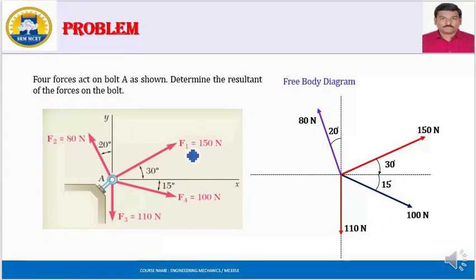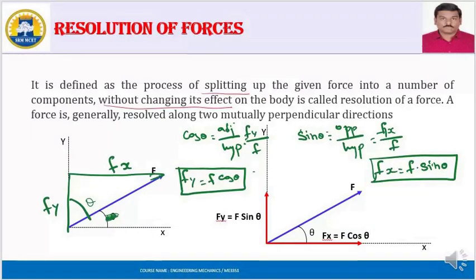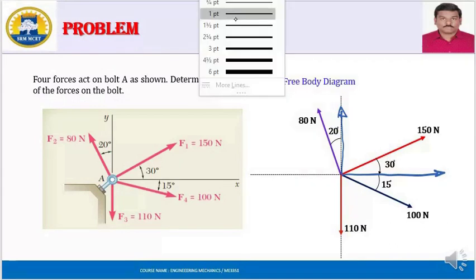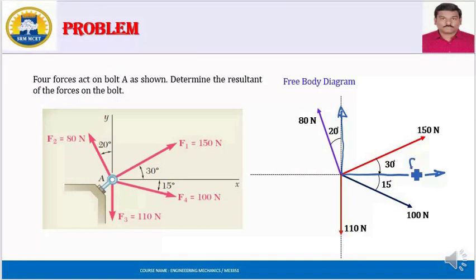Resolution of forces means first you take 150. If I resolve this, I can convert this force into x and y components. Fx is equal to F cos theta, as we already derived.